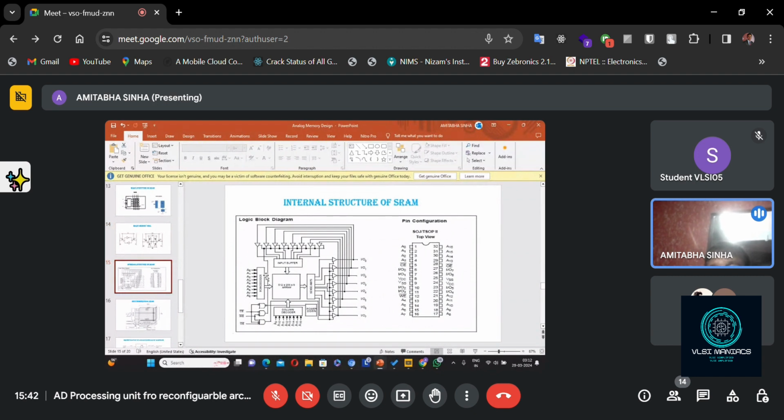And here the normal design is very simple. We have a decoder. This is a basic memory cell where all these elements will be stored, with input lines and output lines. Now this decoder, again we can divide. For example, let's say we have 16-bit address lines. 16-bit address lines means 64K of lines, and the decoder will also be very complex. So you can divide 16 bits into 8 and 8 bits. So row decoder, column decoder, then select one of them. So in that way, your decoding is done.